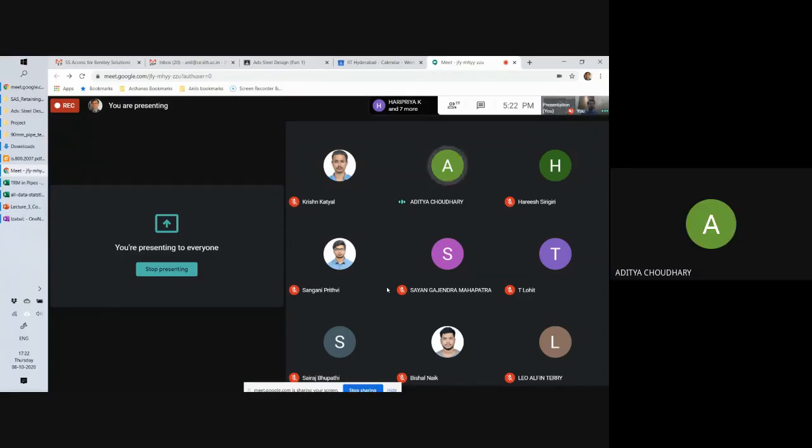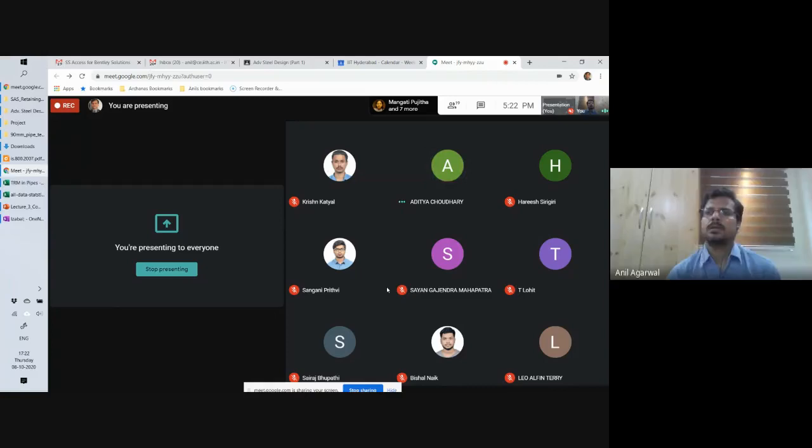Excuse me, sir. Yeah, Aditya. Sir, why can't we use both lacings and battens together in a single column? The idea is that they have different shear stiffnesses. If you mix them, the one that is more flexible will attract most of the lateral force, so most of the deformation will be confined to that area. You want to maintain a uniform shear stiffness throughout the length. If you mix the two, one of them will contribute more, and all the deformations will be accommodated there only.